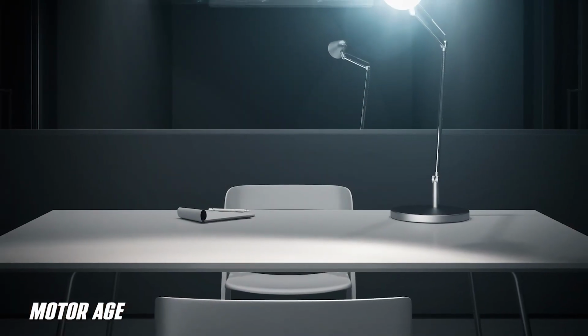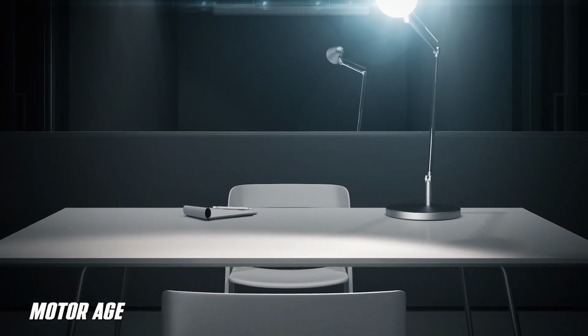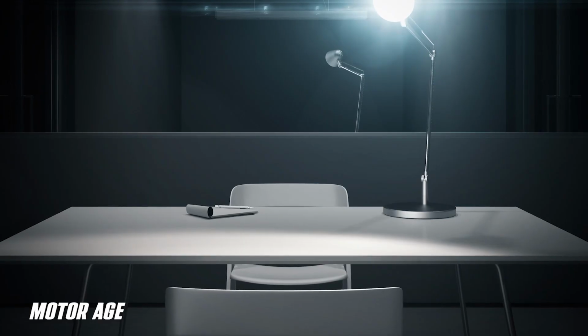So we're going to talk to the customer and determine what the fault is. And like any good investigative diagnostician, we're going to reproduce this concern. We're going to go on a road test and capture the fault. And by way of the customer's perception, the fault, as described, could be a number of different things. It could be a fault related to the engine, a fault related to the ABS or vehicle stability assist control system, and it could even be related to the automatic transmission. All these are real world and very possible for a fault in a vehicle of this age.